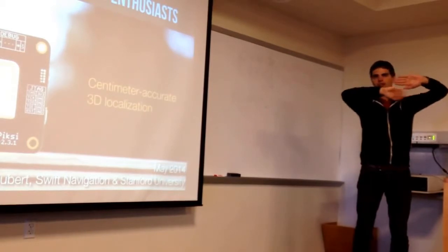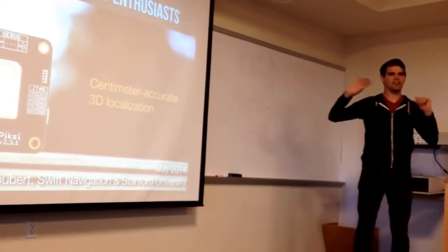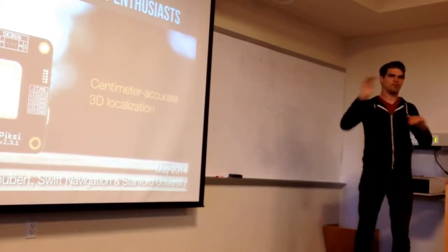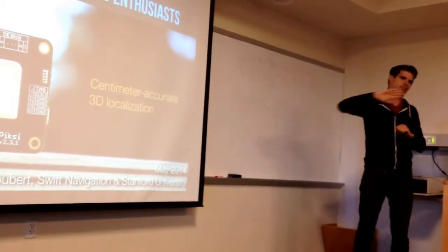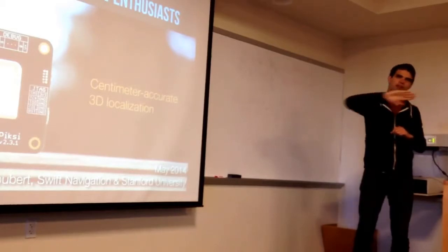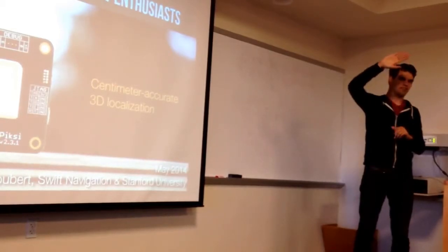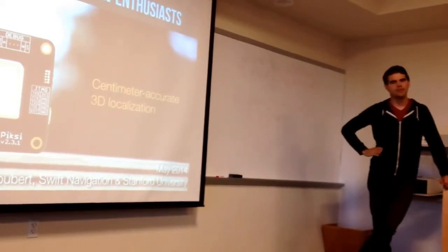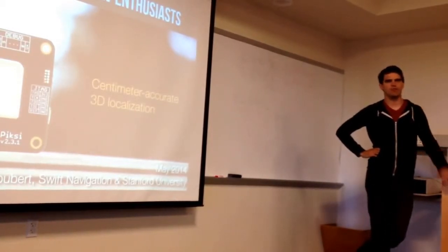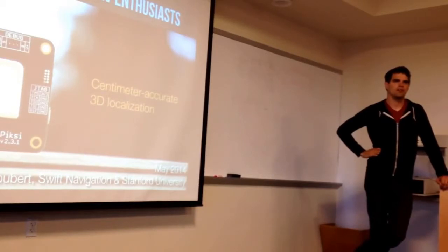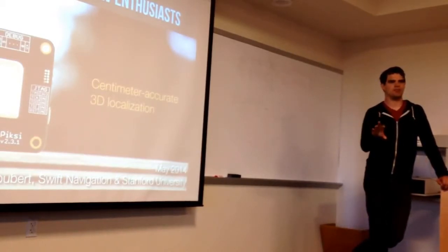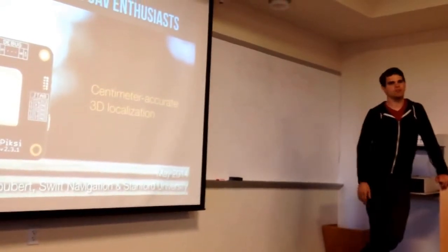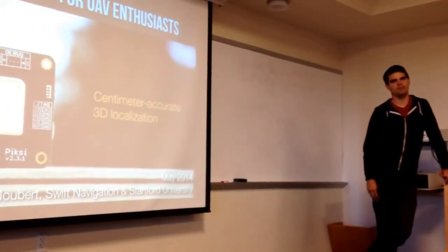The other part I glossed over is that satellites moving at high speed experience Doppler shift, so you have to attempt to align both the PRN codes and then a series of Doppler frequencies. So you have to search in this 2D space, and that's what the custom hardware does. It'll do this for 10 channels or 12 channels or what have you. That's actually what it means when GPS says it's a 12-channel receiver. In hardware, in parallel, they'll align 12 of these elements.